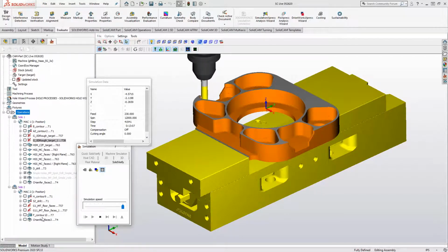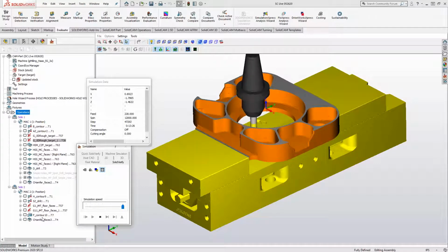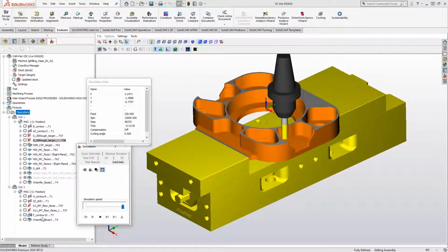So there are filters inside of the majority of our 3D recognition toolpaths to avoid certain things, like for instance, just wasting time going around a hole when really that same tool could have just plunged in there and made that same deburr, that same chamfer. So the smaller holes are probably smaller than whatever I've set as my filter, and that's why it ignored the smaller holes. Hopefully that makes sense.